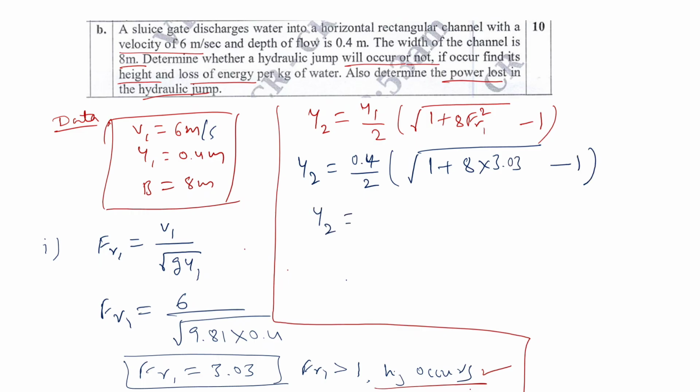After solving this expression, we will get y2 is equal to 1.52 meter. This shows the hydraulic jump occurs at 1.5 meter of depth.